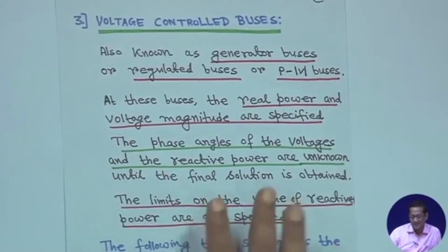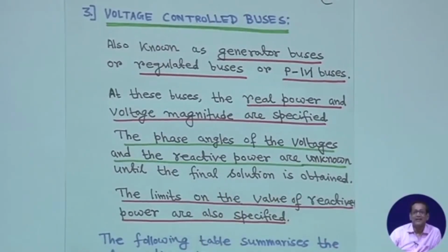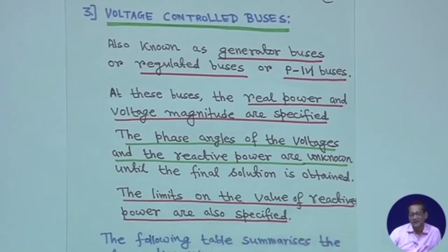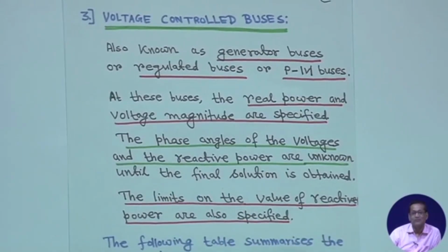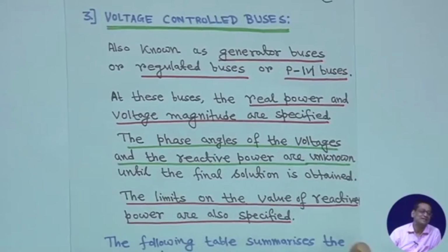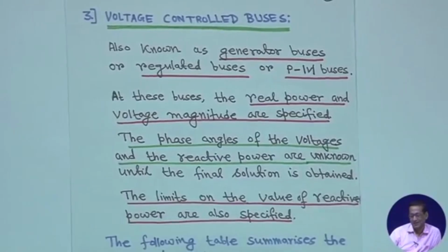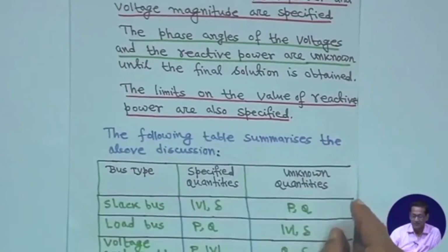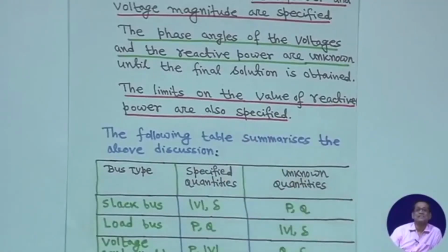It will take a few hours to explain all sort of things, but throughout this load flow study, I will take only one example and give all the methodology. So, the Q limit also you have to consider, and it has to be specified for PV buses.